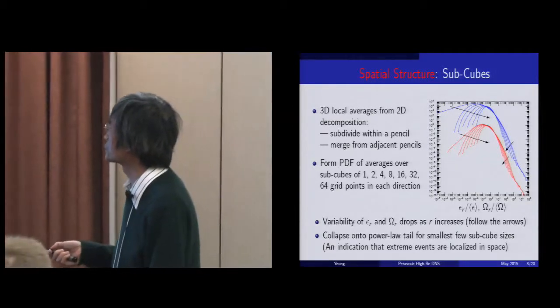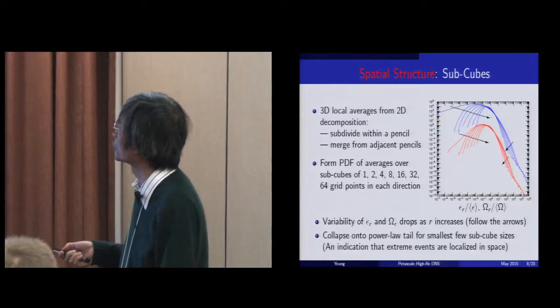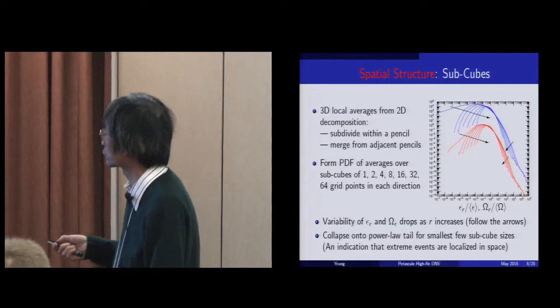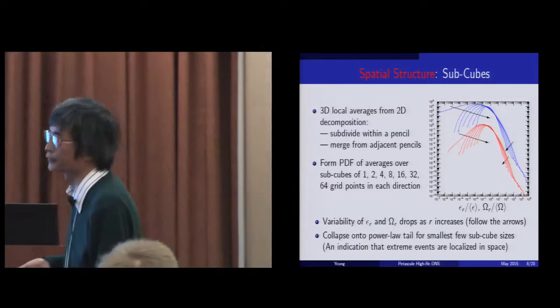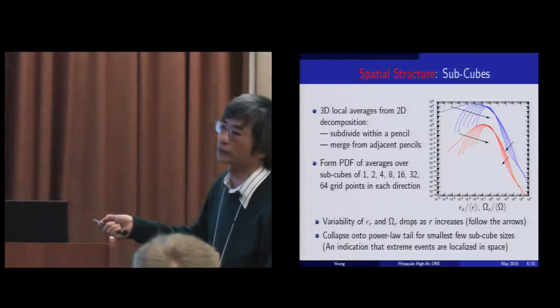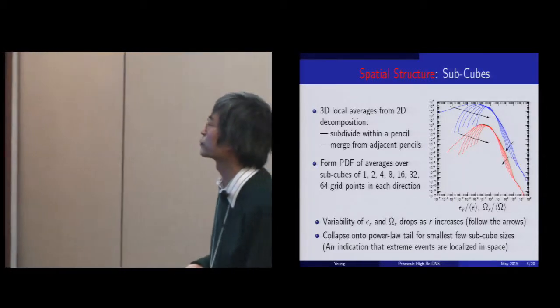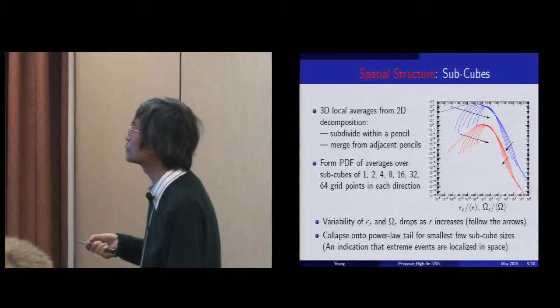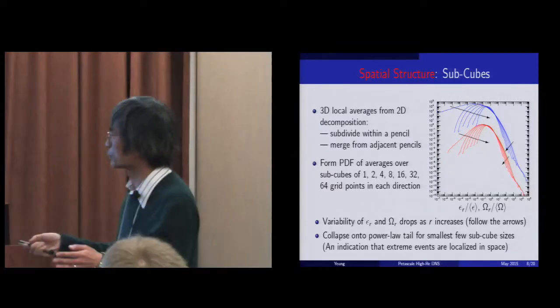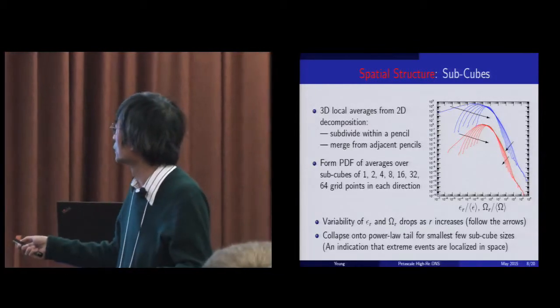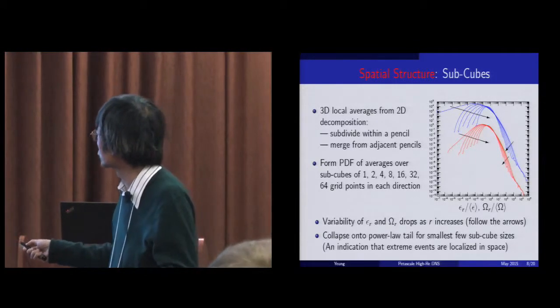And then all of these lines here, the lower set of curves, are all for dissipation rate. The higher set of curves is for the enstrophy. They are not actually that different, but I'm artificially bumping up the lines in blue by a factor of 10 to the 4th so that we can see them on the same graph. The arrows are going in the direction of increasing R. So if you average over a larger domain, then everything becomes less variable. So the PDFs would go like this.